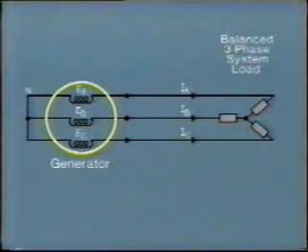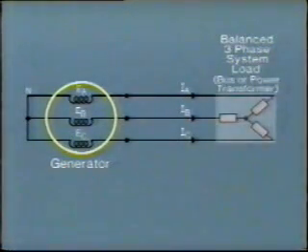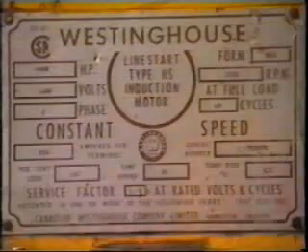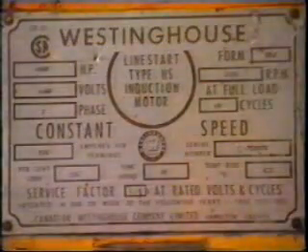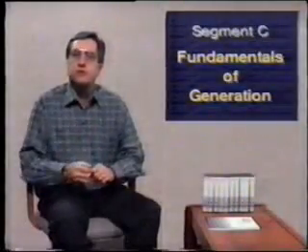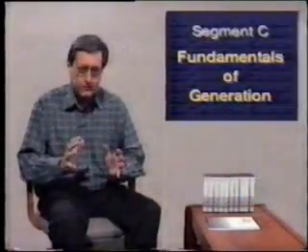We now have the conventional 3-phase system as you know it. The 3 outgoing terminals from the generator are connected by 3 lines to the 3-phase load, that is, the bus or power transformer. This in turn feeds the 3-phase power system. Most of the heavy loads on the system are actually 3-phase balanced loads. For example, electric motors. Moreover, single-phase loads, such as residential loads, are connected to the distribution system in such a way as to provide an approximate balance.